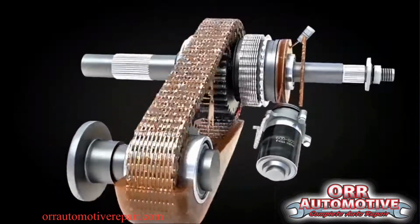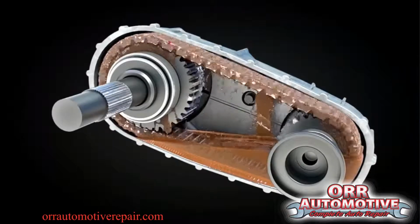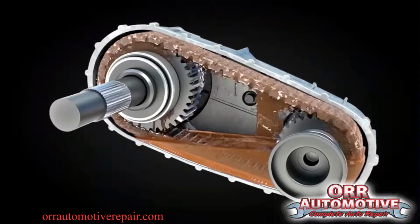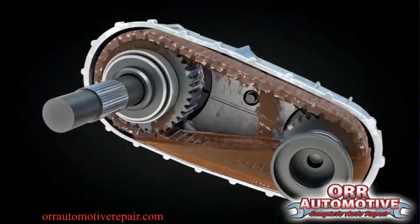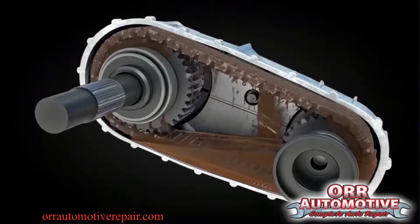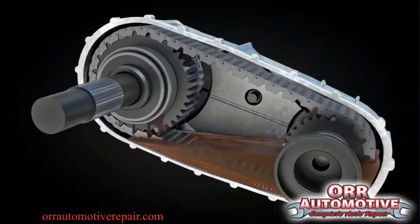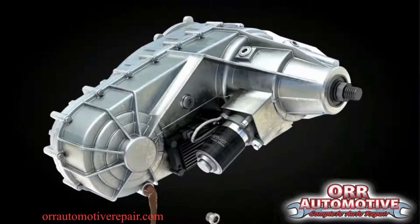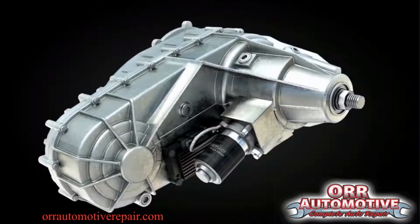The fluid inside the transfer case lubricates and cools the clutches and gears, and usually contains additives that minimize oil foaming and create the correct friction properties. Heating and cooling of the fluid, along with the accumulation of clutch material, can lead to fluid breakdown. This is especially true when the vehicle is used for towing or frequent off-road use. Fluid replacement should be carried out according to the manufacturer's maintenance schedule.